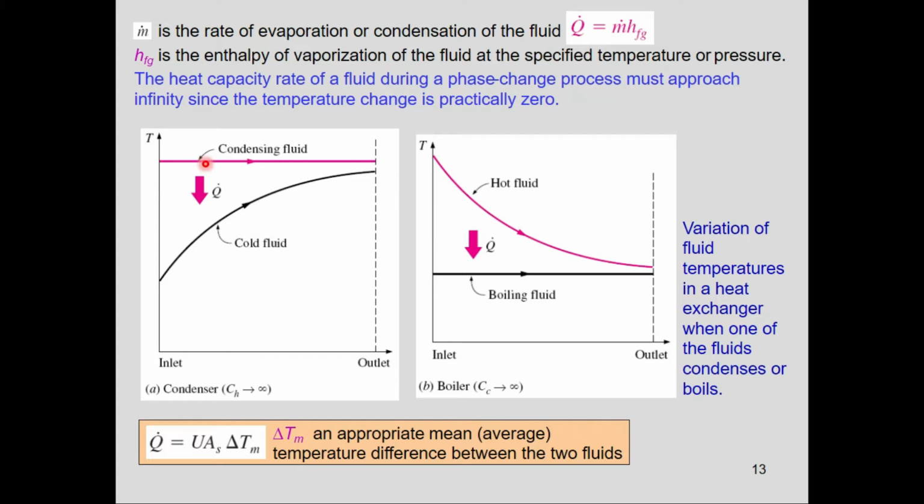One is known as the latent heat, and the other is known as the sensible heat. If the sensible heat changes, then the temperature will change. In the condensing vapors, there is only the latent heat. When the latent heat changes, only the phase change occurs and the temperature remains constant.